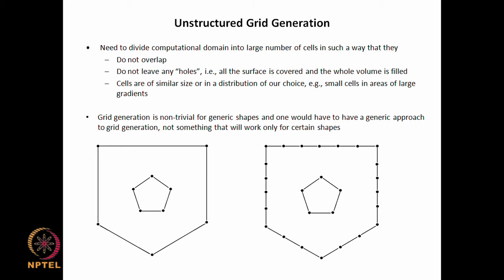They should be roughly of equal distance from each other, and obviously they should not be very close to the boundary surfaces, because if you had a point here and then joined it like this to make a triangle, then you would have a highly distorted triangle, and something like that is not very desirable. So, you would like to have a method of placing the interior nodes in such a way that they are distributed all over the computational domain, and that there is a sufficient gap between the points and between the points and the boundary.